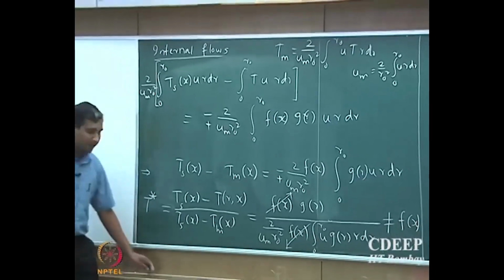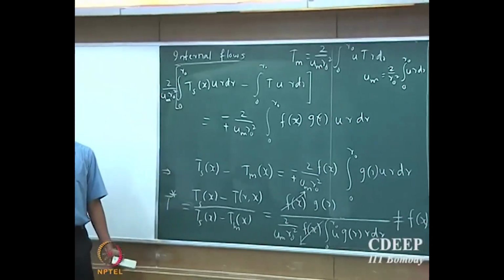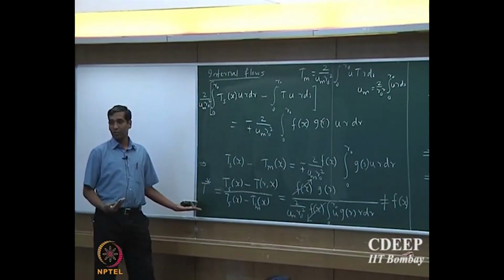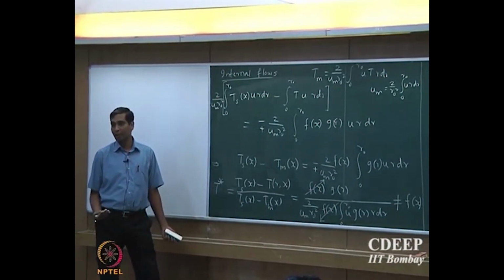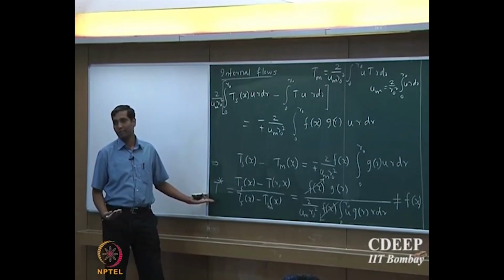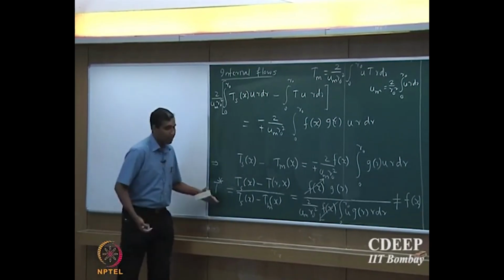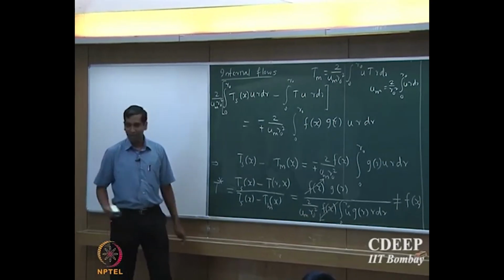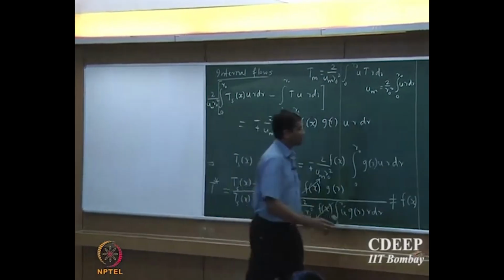Okay. So this is a fundamental difference between the momentum boundary layer and the thermal boundary layer in the internal flow case. So it's not the temperature profile which is not changing, it's the dimensionless temperature profile that doesn't change with the axial position. So this observation can lead to some really interesting and intuitive results, which is what we will see in a short while.